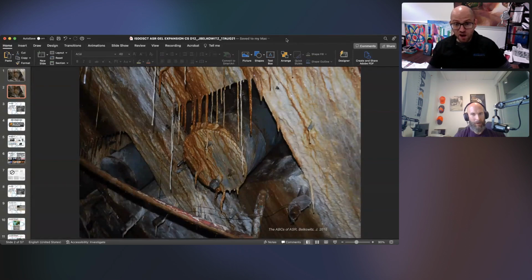So you have this combination of failures. It's rarely ever the ASR gel that causes primary failure. It's normally something that pushes the snowball down the hill, right? It starts the failure mechanism. It's not the straw that breaks the camel's back. It's normally the steel failure.